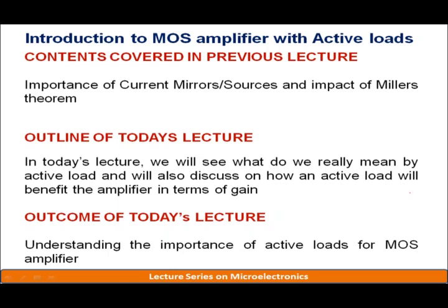Now, one of the straightforward elements that comes to our mind is, why not we replace the resistor with a current source itself. Now, again, the current source that we typically use in the laboratories, we cannot be using that. Of course, we can use those things when we will be doing the discrete experiments. When I do the experiment in the labs, possibly I can be using a discrete current source. But if I want to build the entire setup of the amplifier in an IC, then possibly the discrete current sources would also fail. Hence, the only option left is to build the current sources using MOSFETs,